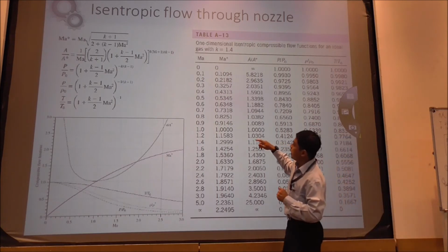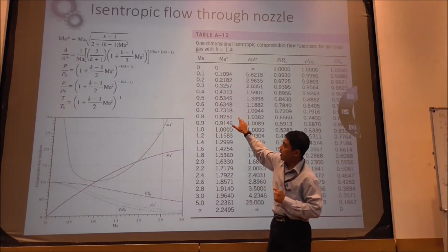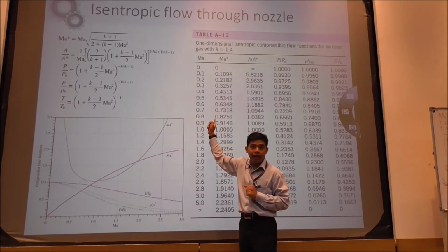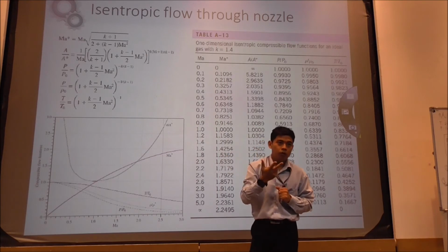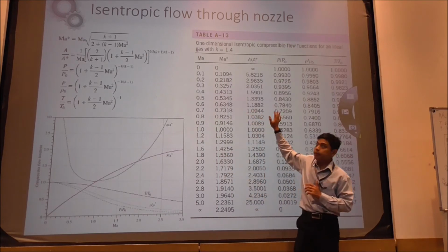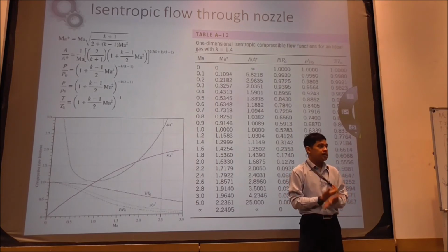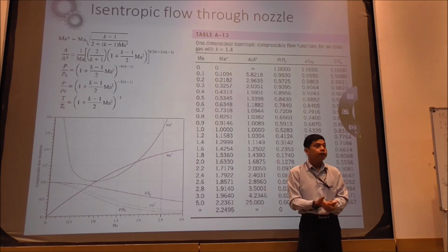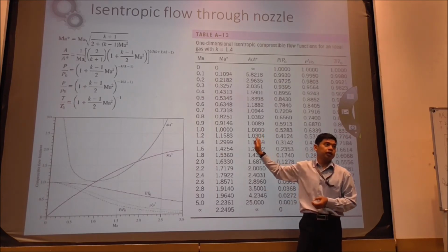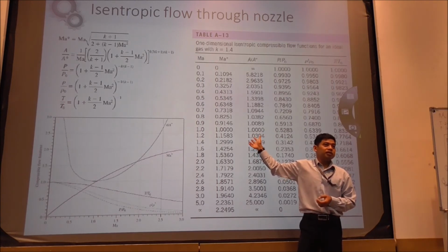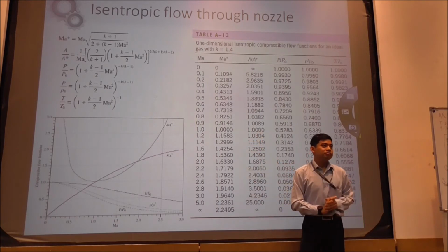So you can see that this table and that equation will give you the same value when k is equal to 1.4. So this table is only applicable for k equal to 1.4. What happens if my k is 1.667 or 1.3 or 1.47 or some other value? You cannot use this one anyway. This one will not be applicable. But sir, I'm so desperate during the test, I will use it. It's up to you.